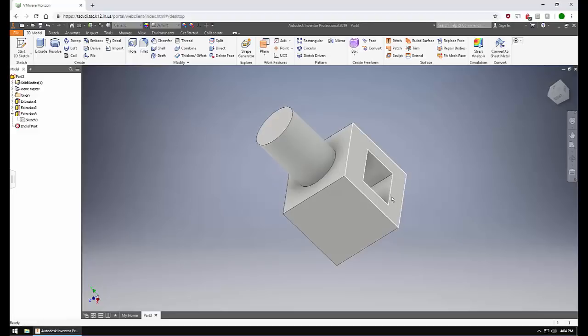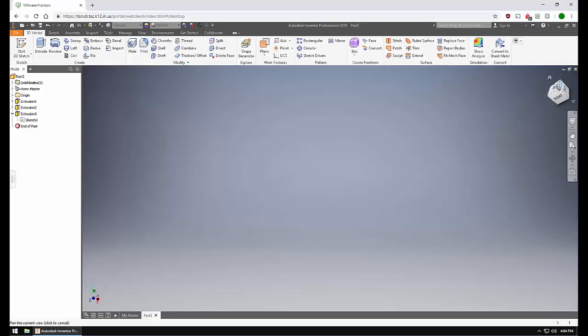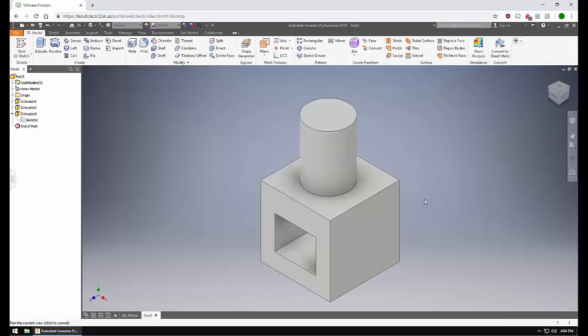If you ever lose your shape, you can click on the Home button near the top left of the cube. You can move the small bar on the left by holding the left click button and moving it up and down. There are also several shortcuts you can use when sketching. Hitting L on the keyboard selects the line tool, for instance.